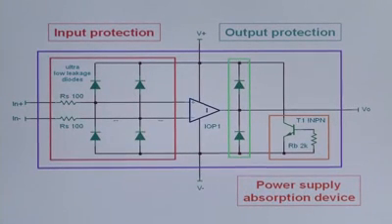An ESD event is very short, typically 200 nanoseconds or less, and the entire circuit is capable of dissipating the power associated with the event. Now, this same integrated circuit with this protection can be damaged during an EOS event, especially if the power supply transistor turns on.